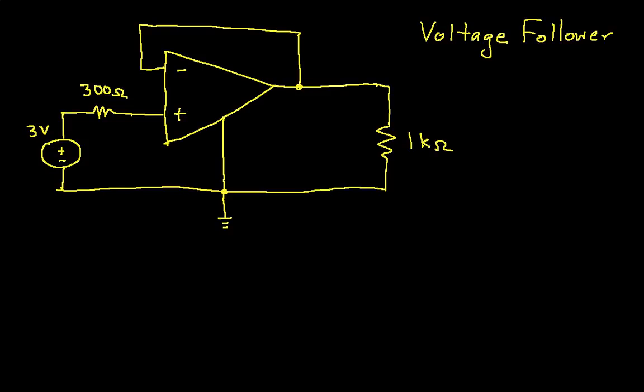First, we'll use the realistic model, sometimes also called the non-ideal model, where we have an input resistance. In order to show you how this works, I'm going to make the input resistance fairly small relative to what it would actually be. I'm going to have it just be 1 k ohm.